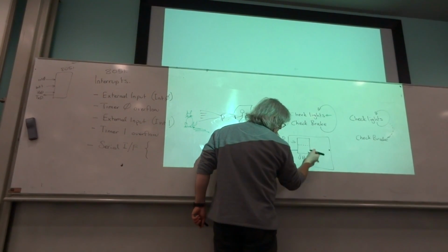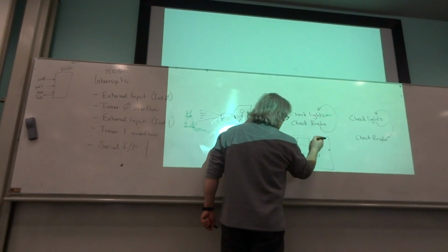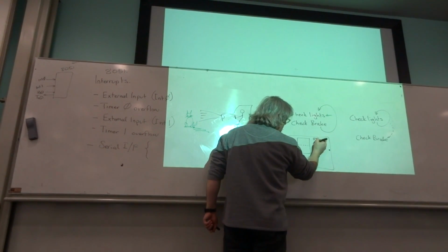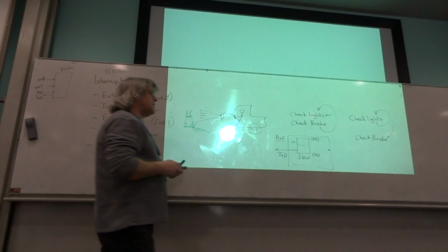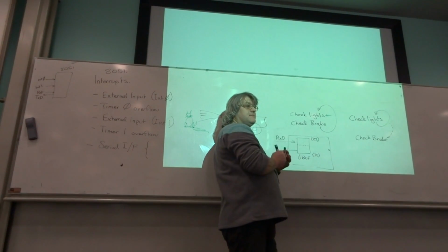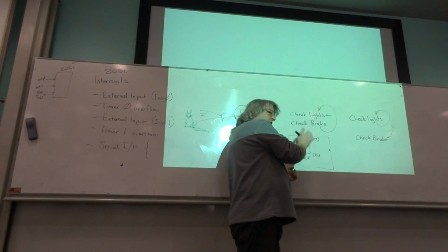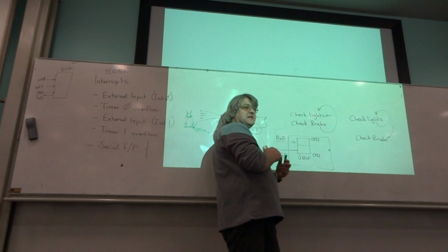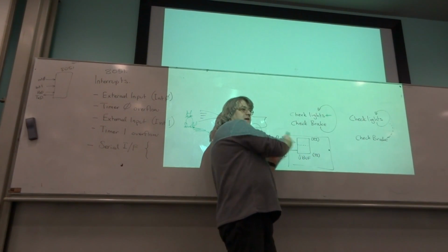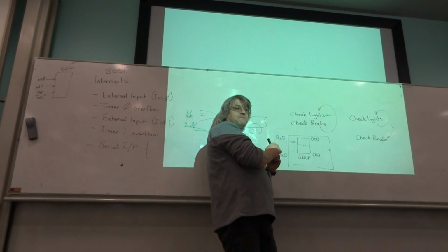On this side of it, for things going out, there's a flag called TI, transmit interrupt, and on the input side, there's a flag called RI. How many bits is SBUF? How many bits is the buffer? Yeah. It's 8 bits. It can be 8 or 9 bits, but usually 8 bits. So what would normally happen is you write to SBUF, it will automatically go into here, and things will be transmitted. As soon as you write into here, it starts to get transmitted. When the transmission is complete, this flag will go high.